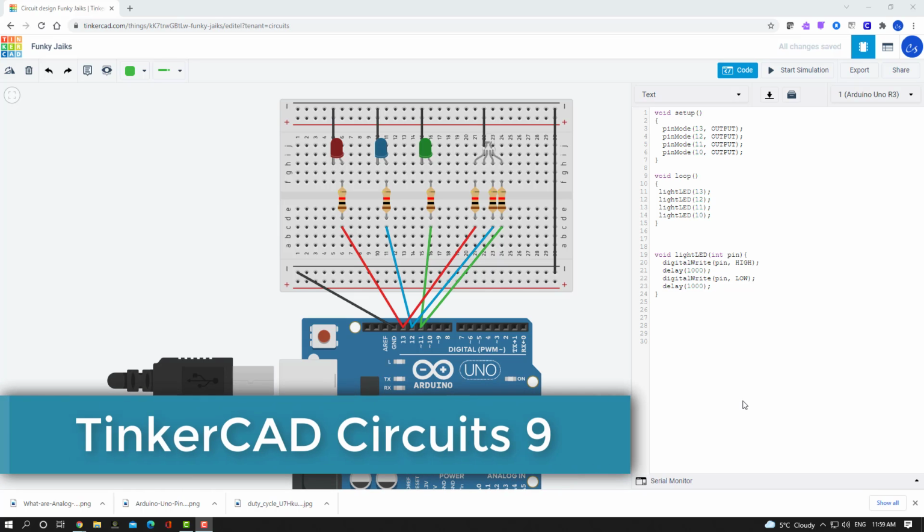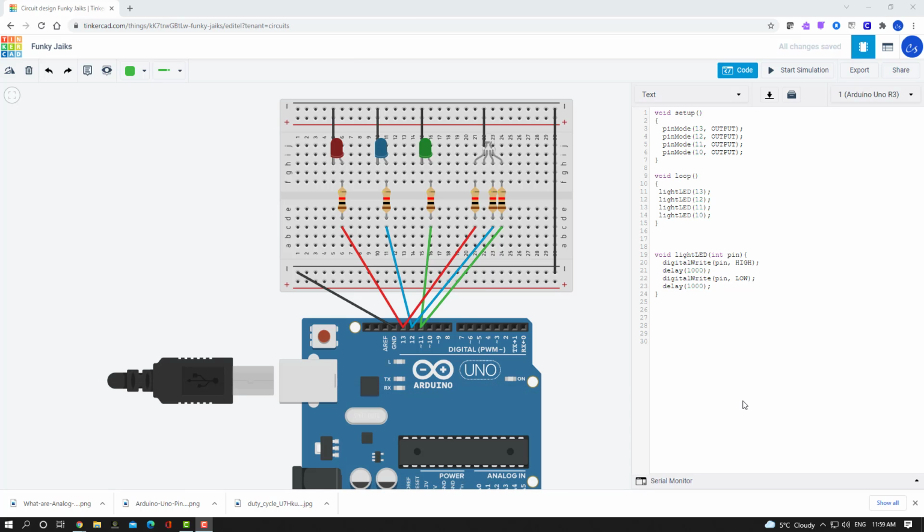In the last video, we looked at how to use an RGB LED component on our breadboard, and we just sort of split the signals coming off of our pins 13, 11, and 10, just using the simulation, something we talked about in the last video that you couldn't really do in real life. You'd have to use the breadboard in a different manner. But for the purposes of learning today, we might as well take advantage of that in the simulation environment and just go ahead and split a pin into two directly off the Arduino.